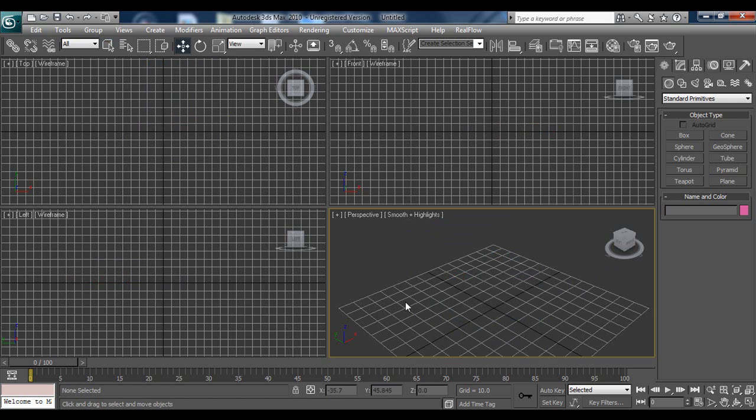This is the select and move tool, and it works on the X, Y, and Z axes. You can move up to the right, or do X and Y spaces, as you can see here. Again, we've got a rotate tool. This is particularly useful when used with the angle snap tool, as it allows you to rotate things to a certain degree. Whenever this is off, it can be rotated down to a degree, but whenever it's on, it goes around in 5s. So it allows you to get degrees like 90 perfectly.